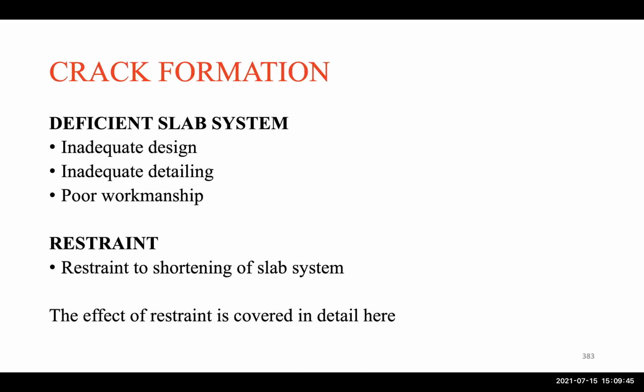Disasters will happen, and that's what happened recently, unfortunately. So this could result from an inadequate design from the beginning, or inadequate detailing. Detailing is extremely important. It's not only how many tendons or how many rebars we need, but how we detail that in the structure.